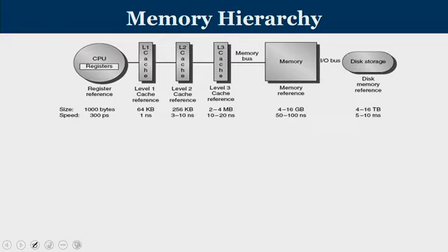If you look at the CPU, it has internal registers. That's what we have seen. We have integer registers and we have floating point registers, which are marked as R for integer registers and F for floating point registers when we were going through the topics of instruction pipeline. So these registers are very fast, CPU can access them. Generally, wherever possible in our programs, we try to keep our operands in the registers, and you can see that it's not possible to have a huge set of registers. Generally, the registers are in the order of few bytes, and accessing registers is in the order of picoseconds.